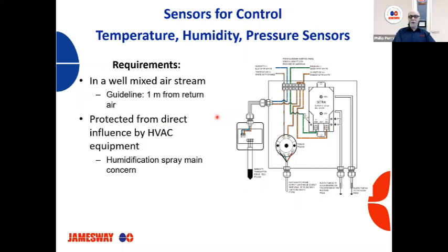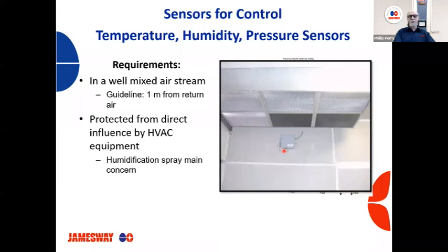If it's spraying on an RTD probe, it causes evaporative cooling, causes a lot of cycling within the room. It can also affect our humidity, as it comes on and off. So again, we want to have it away from anything that might cause it to not read properly or to be over what it would do to certain conditions of the room.